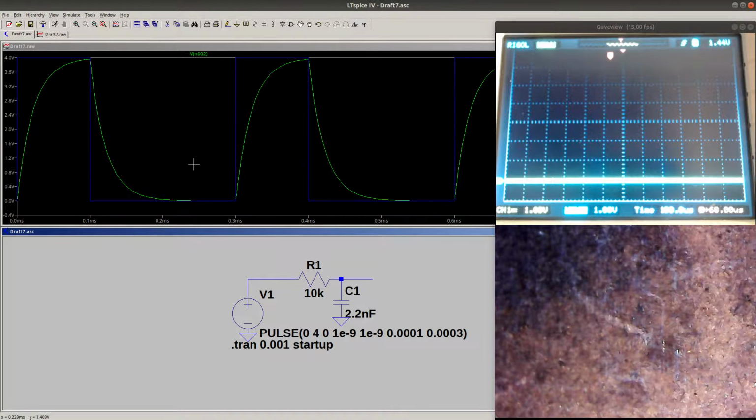That's better. So what we have here is a first order system, a low pass filter, and it has a slope that looks like this. And from this slope, it's even possible to tell the transfer function of the system. A transfer function is a function in the frequency domain that describes the dynamics of the system. If we have the transfer function of the system, we can simulate the system, and we can implement different types of filters that depend on knowing the model of the plant.